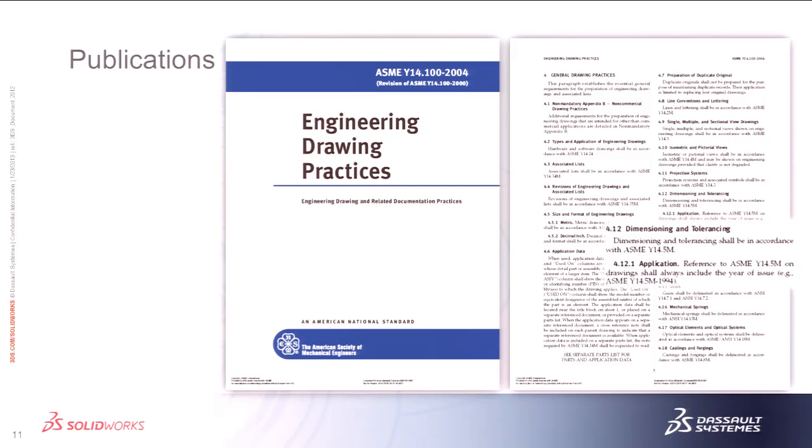With Y14.5M, it's stated in both Y14.100 and the 14.5 that if you reference that on your drawing, you must include the date with it. That's because there are significant changes in the way that drawings are interpreted from one revision to the next. They bring in new symbols, they remove symbols. So 14.5 must include the date.